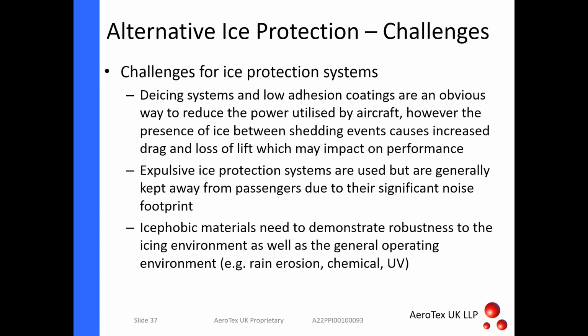So de-icing and low adhesion is an obvious way to reduce the power, but it does affect the performance of the aircraft, because you're letting ice grow, so therefore it's causing more drag. The expulsive systems are really noisy, so you don't really want those next to your passengers, because I think it would terrify them, quite honestly. I've been in a tunnel with them, and they're very, very noisy.